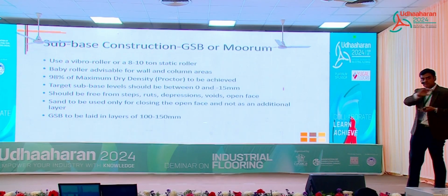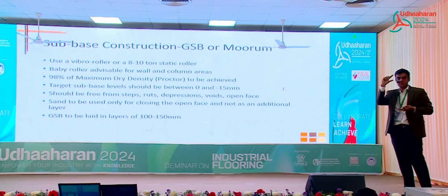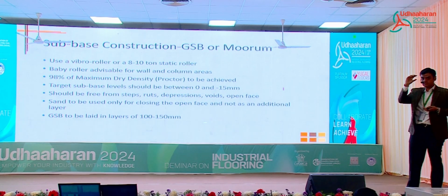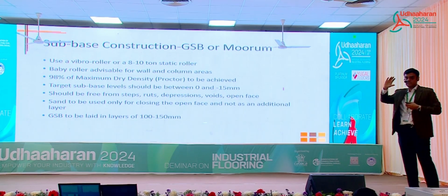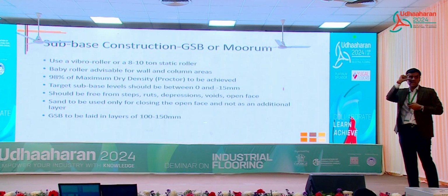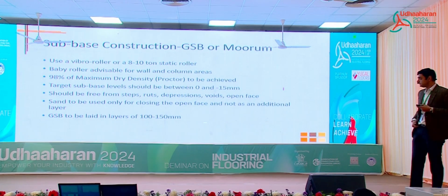So we don't look at an average thickness, we look at a minimum thickness. This is a very important point. If the client is insisting, "I just want to spend this much," then it has to be clearly communicated that we are talking about average thickness and not minimum thickness.